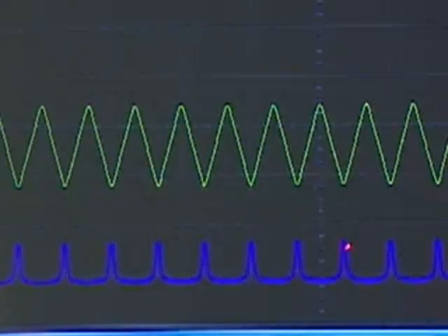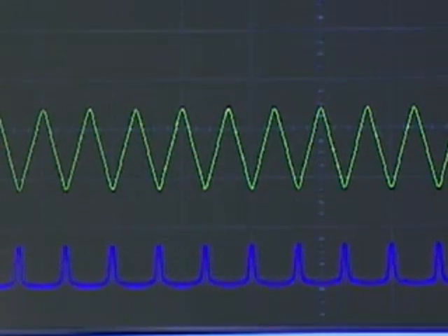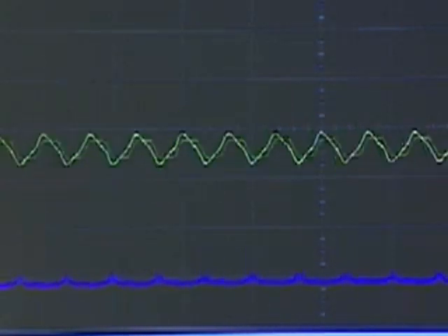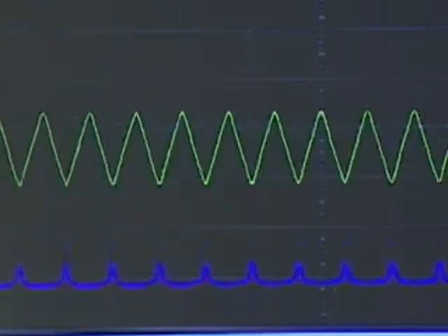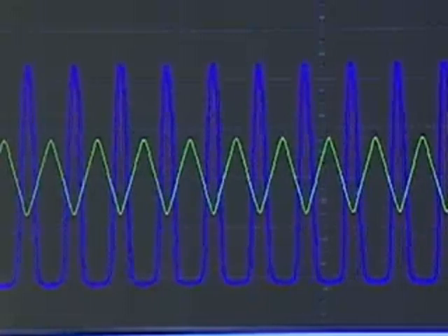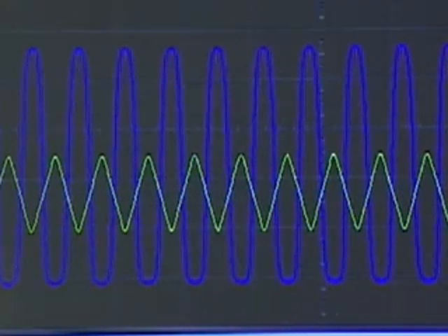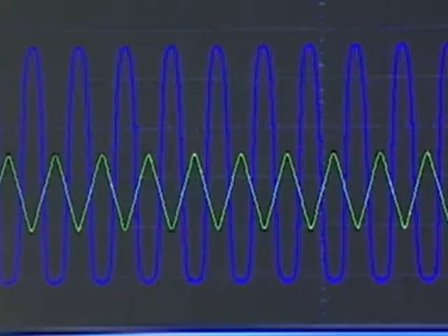So notice that as I boost up my input even higher, the output is a really small image of what the right input should be. Okay, the right answer here, of course, is that I apply some right amount of offset to boost up the input into the right regime so that the output is seen to be some amplified version of this input.